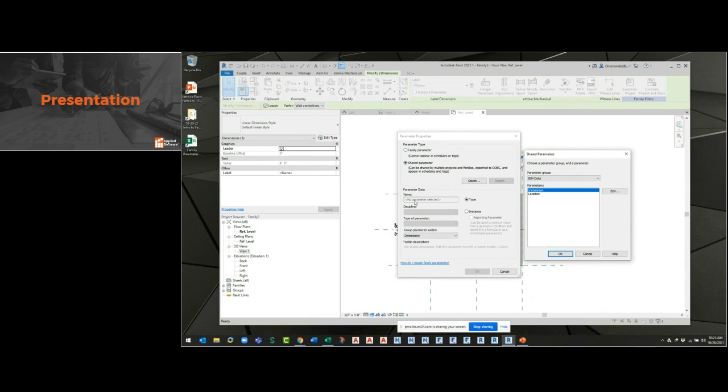Bob calls it inst and loc or something. And there's 3 of the same parameter, but all 3 of us on the same team created them differently, right? That's where shared parameters really come in, and it will help with managing your standards in-house, as well as for schedules and tags. So, you can make sure that your schedules and tags are all populating with the correct information.